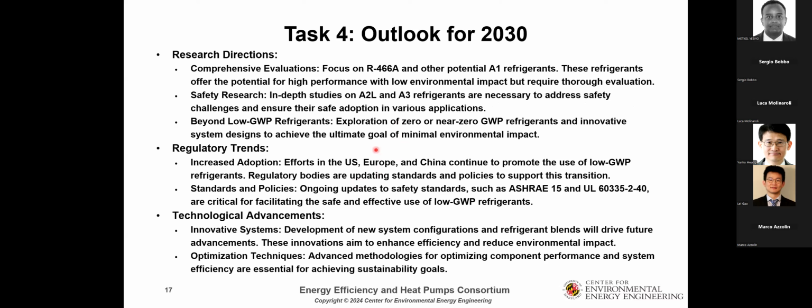In terms of regulation, we will consider globally the low-GWP refrigerant adoption and the standard policy, the safety standards such as ASHRAE 15 and the UL standard. And in terms of technology advancement, we will still look for innovative system design and incorporate the optimized techniques into this system design.